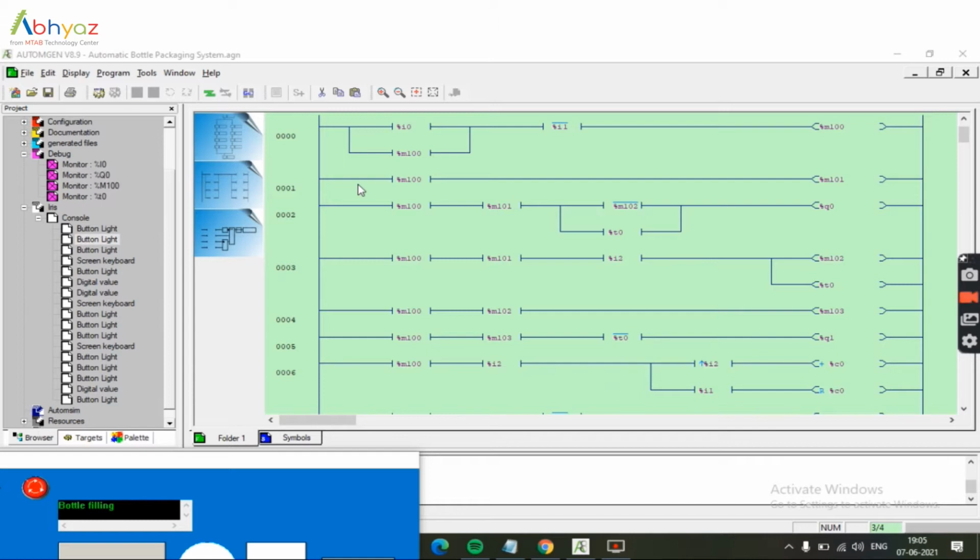It transfers the memory value from the power control memory bit to the first user memory bit and controls the conveyor motor. In the list of components, we have 3 conveyor motors, as in the solution which we had given for the problem statement. We use 3 conveyor belts, and adjacent to the belts there are 3 respective stations, that is the filling station, the capping station, and the dispatching station. The power control memory and the user memory control the first motor.